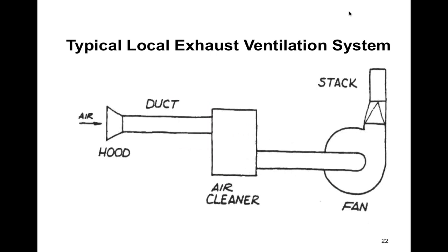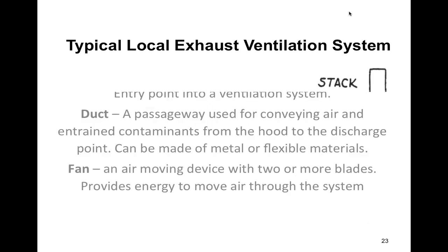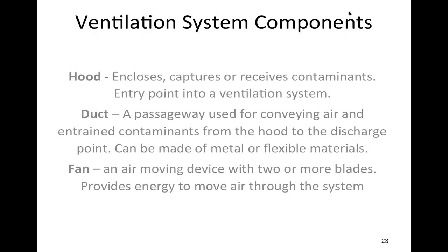So they have an informal, small exhaust hood over it, that kind of captures stuff as it goes up because it's a warm solution. The air rises, captures most of it, and controls the odors. But they don't really have a well-designed hood to capture everything and take it away from them because, based on their measurements, it's well below the permissible exposure limit for that material.